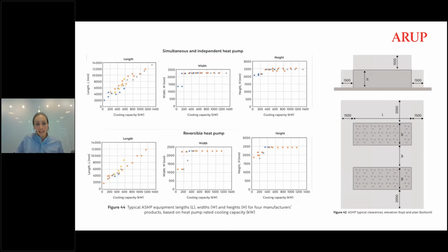So once you've defined your loads and selected your technology, you then want to size the different bits of kit. And I particularly wanted to talk about one bit which I get a lot of questions about, and what can be quite challenging: early in the design stage, designers often struggle to work out how much space might need to be allowed for air source heat pumps in particular, because air source heat pumps require a certain amount of quite high demand outdoor roof or outdoor space.